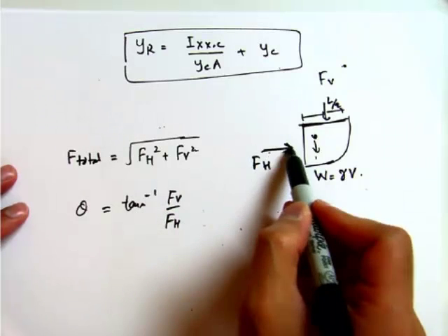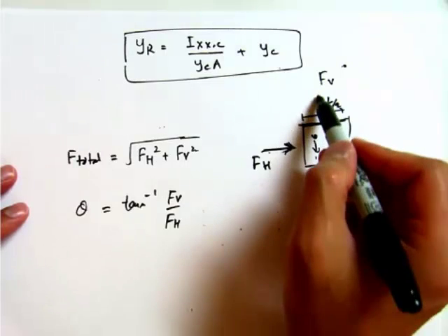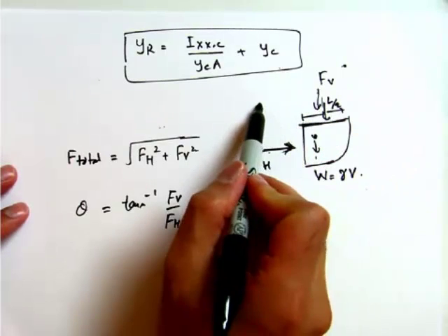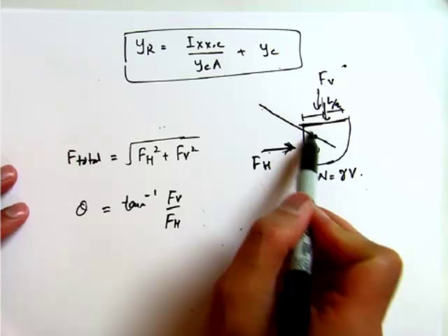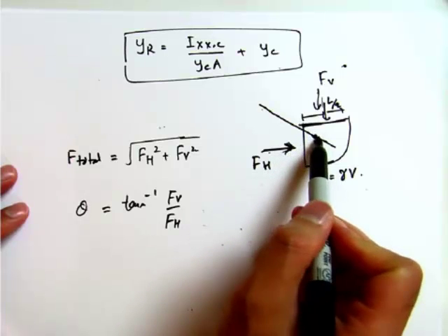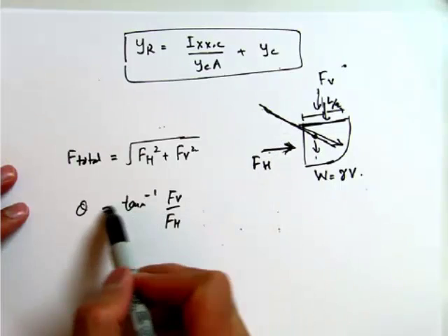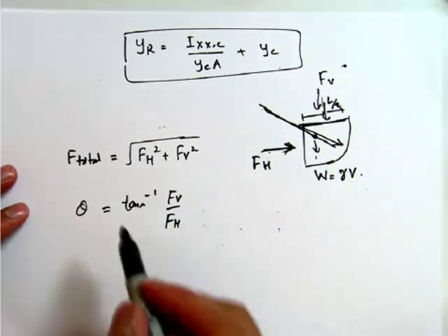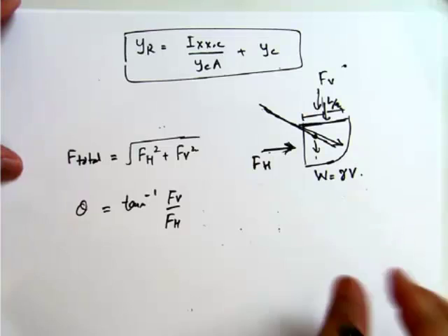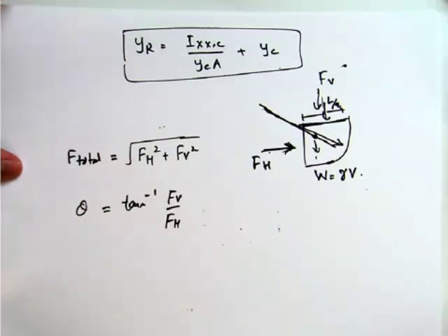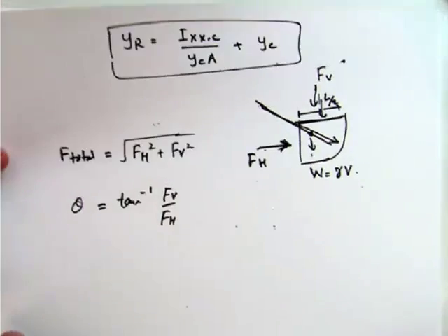So you have a horizontal force acting this way, you have some vertical forces acting this way, so the resultant will pass somewhere over here. So this will be given by this angle theta. So you can basically compute that theta and you have the magnitude for the total force. Alright, so let's take a look at a quick example for this one, for a curved surface.